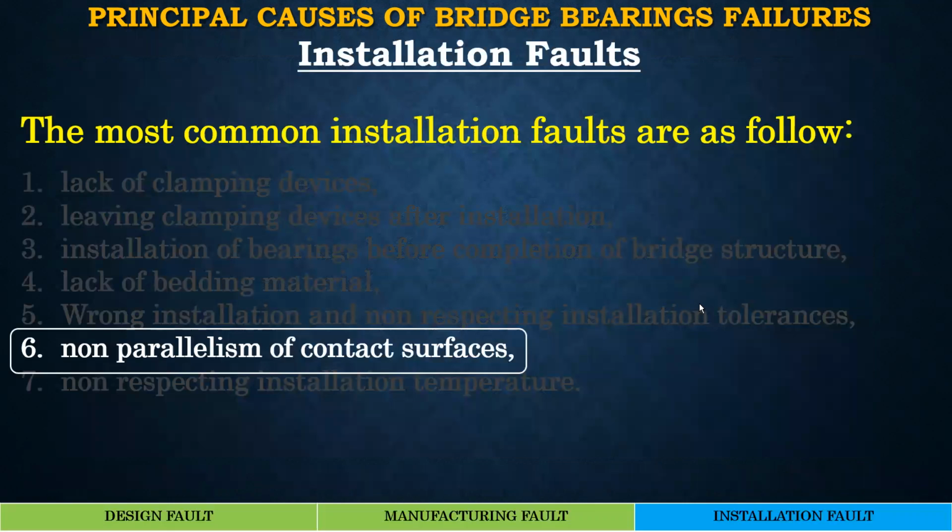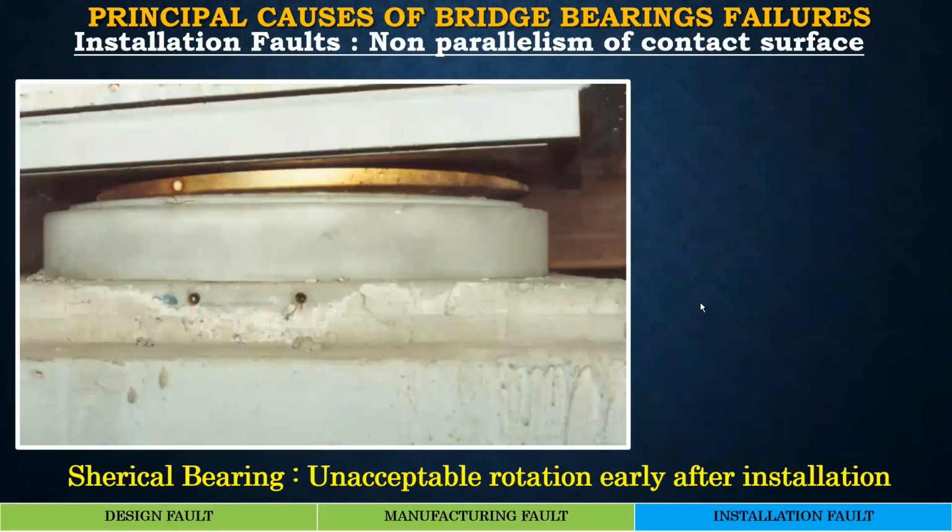Coming to non-parallelism of contact surfaces, spherical bearings, you can see there is a slide which shows that if your top and bottom surfaces are not parallel and they are not leveled, it can cause, at the installation stage itself, an unacceptable rotation. You can see that already the top plate is rotated by a very large angle here, which is unacceptable.